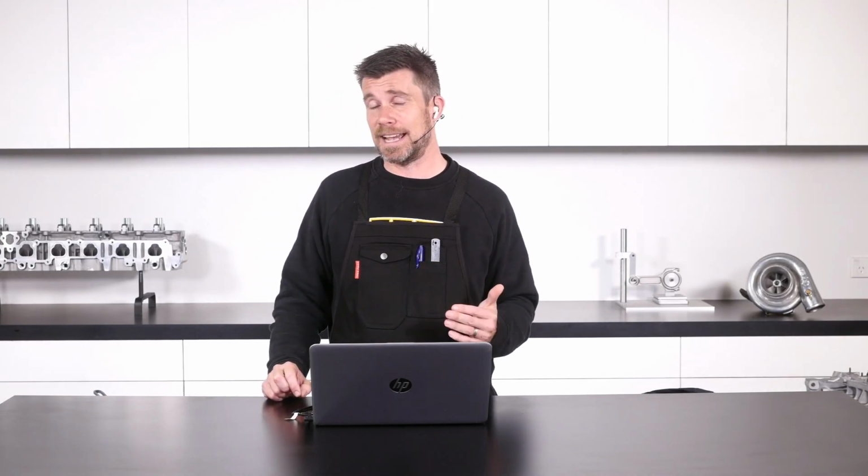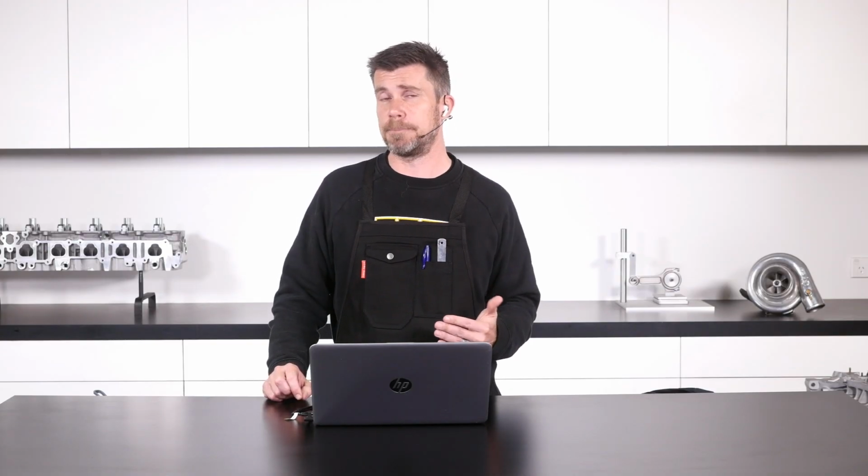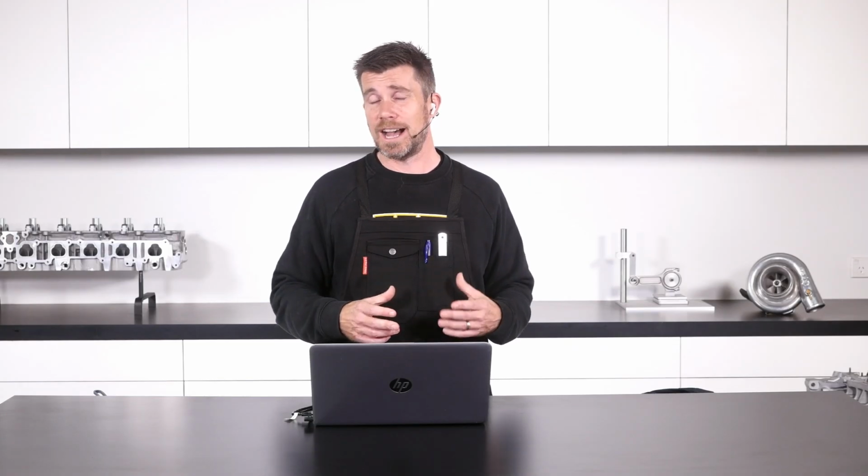An interesting phenomenon that has come out over the last probably decade or so: we've seen a massive advance in turbocharger technology, and we are actually starting to see some really impressive results from even T3 framed turbos, where the exhaust side is a T3 flange, yet they still are making massive power levels that would have been previously thought impossible on a T3 frame turbocharger with manageable levels of exhaust back pressure.